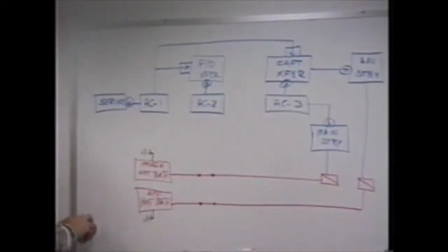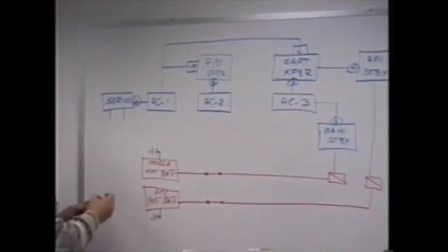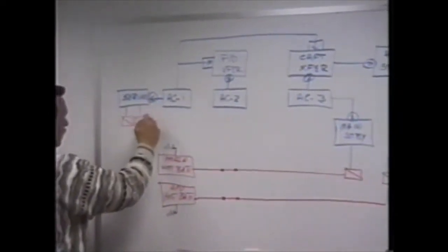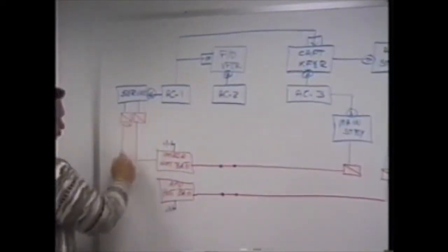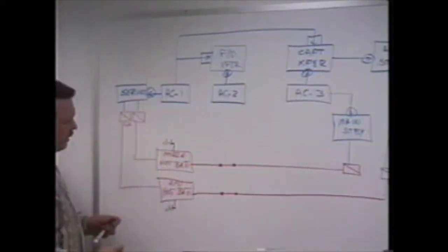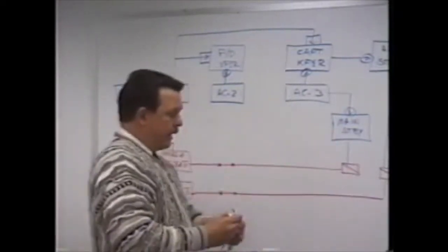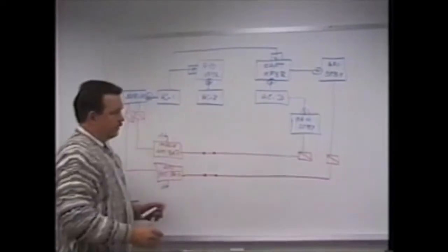The service bus gives us our two chargers. If the service bus is powered, your battery chargers are running, which are actually physically powering your hot battery buses and in turn powering your standby power system. In order for this power to occur, the battery switch must be closed.